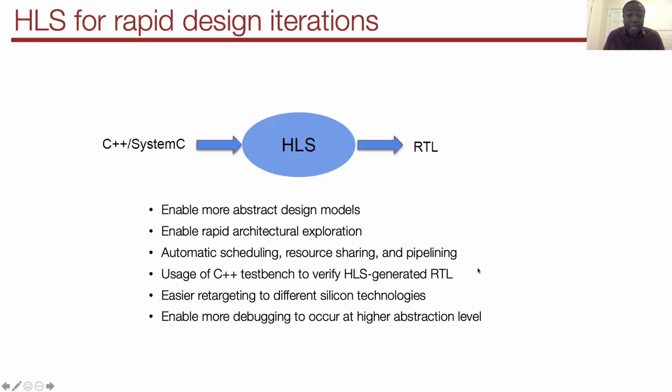And I think one of the major benefits of HLS is that it allows you to use the C++ test bench to verify the HLS generated RTL. So there is no need to create a separate RTL test bench to verify the Verilog produced by the HLS tool. I think this is very important.